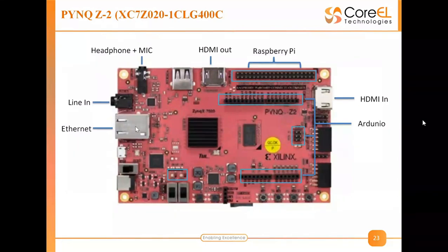That is here. This is the JTAG or UART. This will be in normal mode. We'll use this to program the board. But in our case, the bitstream is already there on the SD card, so programming is not required. But two-way communication between my laptop and the board is required. That is where this UART protocol comes in. It helps in two-way communication between the board and my laptop and the laptop and the board.